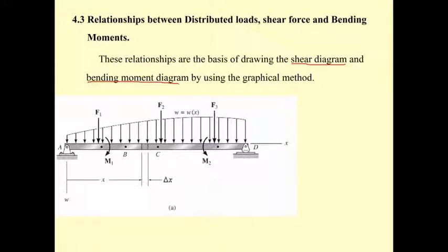If we cut the section and set the coordinate x, for example, as a variable, then from the second clip we can determine the function of the shear force and the function of the bending moment. With those functions, we can draw again the shear diagram and the bending moment diagram, and find Vmax and Mmax.